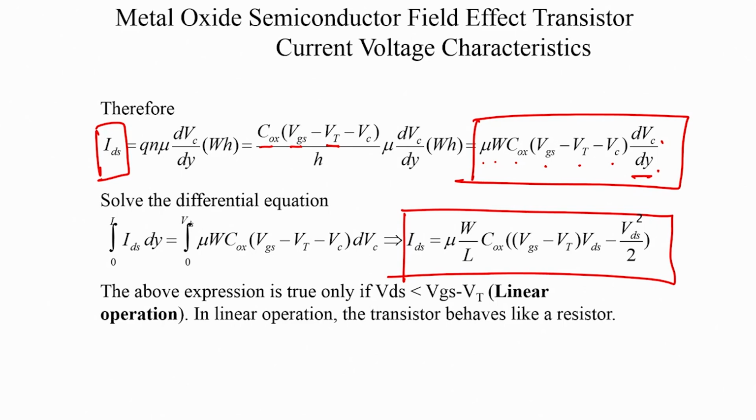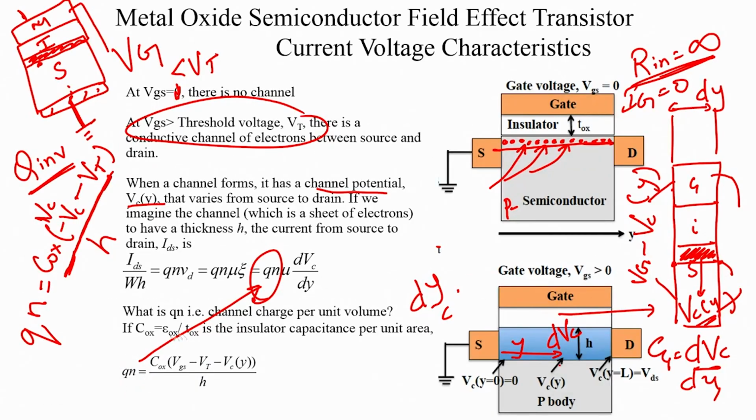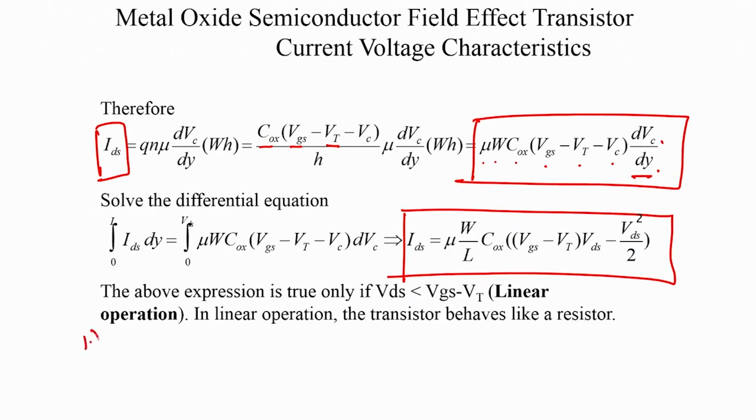But there are a lot of problems in this. Okay, so, many assumptions made, many implicit assumptions made. So, what is the first assumption that we have made here? The first assumption is the fact that we have actually used this expression for drift velocity. When is this expression valid? This expression is valid only under low electric fields. So, that is the first assumption. We have assumed low electric fields,